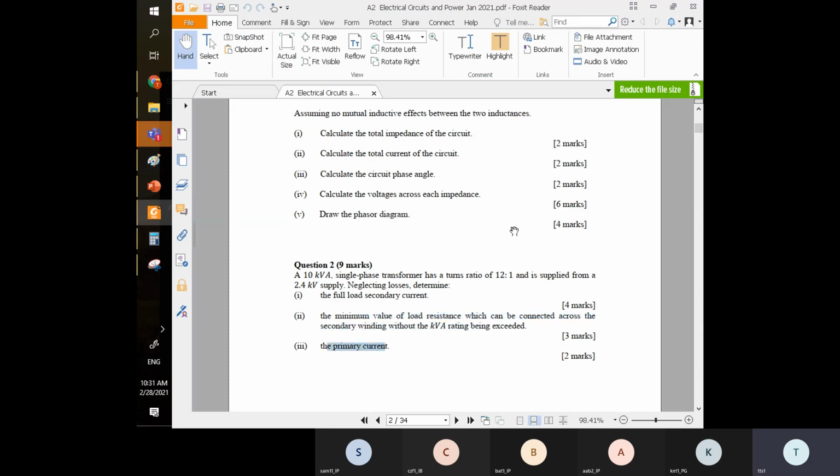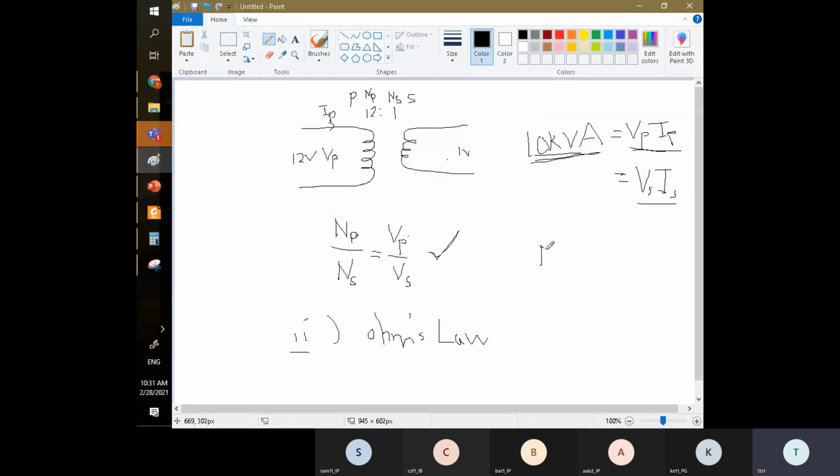I give you the equation here. The turns of the primary over the turns of the secondary for the current is opposite, because when the voltage reduces, the current should be higher. When the voltage is dropping, the current will go the other way. Just like your car battery, when you're in a short circuit, voltage will drop to 0 and current will shoot to maximum. So they are opposite each other, right?